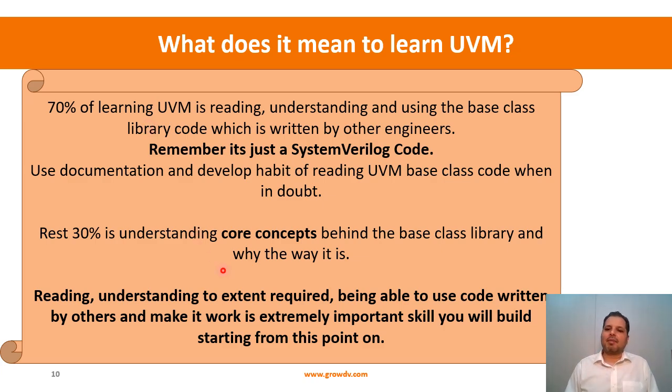The core concepts bind all these base classes. The good thing about UVM is that somebody could have specified only 30% core concepts and left the rest to be implemented the way you want, right? But they have not done that. They have specified some concepts and made those concepts concrete by providing base classes, so that there is a guideline in the form of executable code. It is not just something verbal. They are providing the guideline as executable code, so that the guidelines recommended through the core concepts become reality.